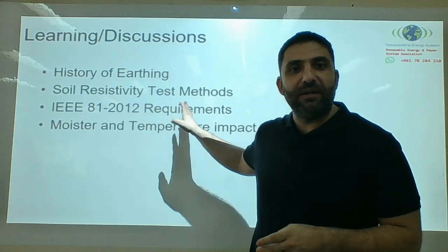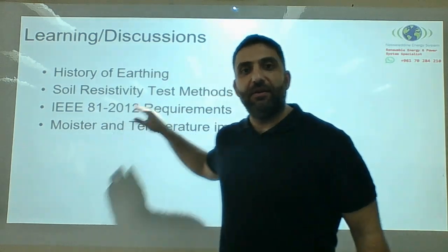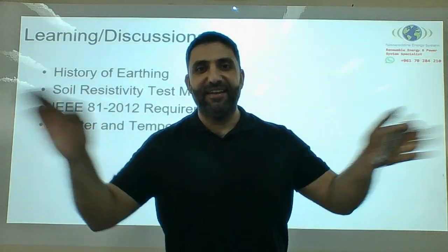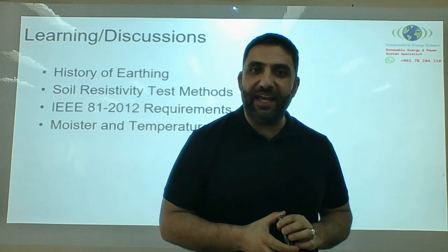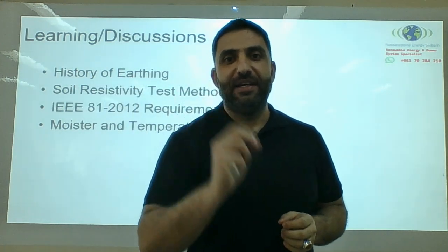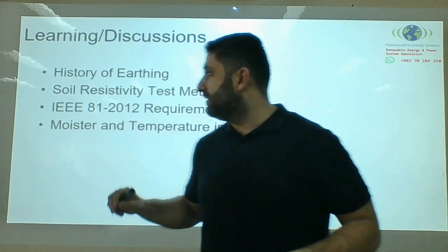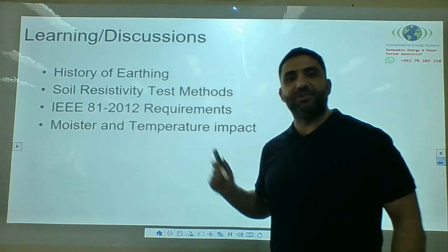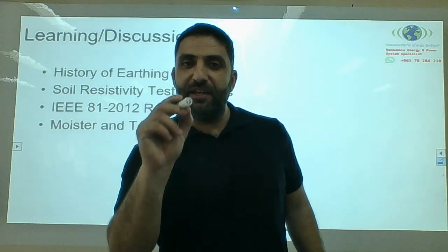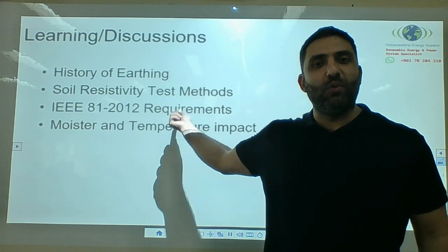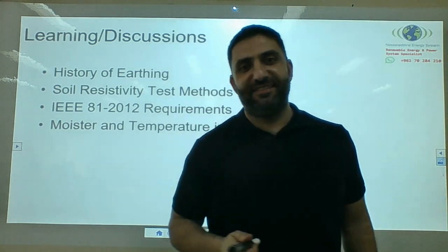When it comes to Wenner, the most used one, we provided you with a table regarding the desired A in respect of the length of your substation earth grid regarding the error. Also, we showed you the moisture and temperature. It's very critical to take into consideration the weather condition when you do your test.